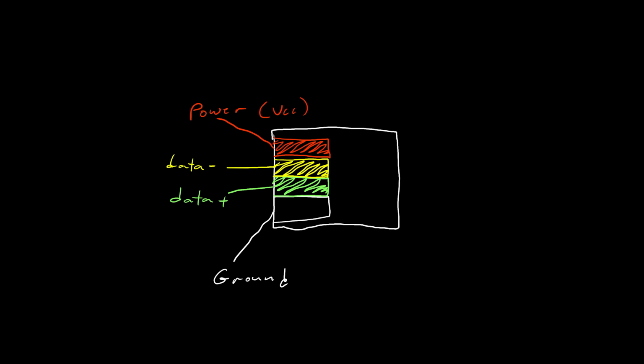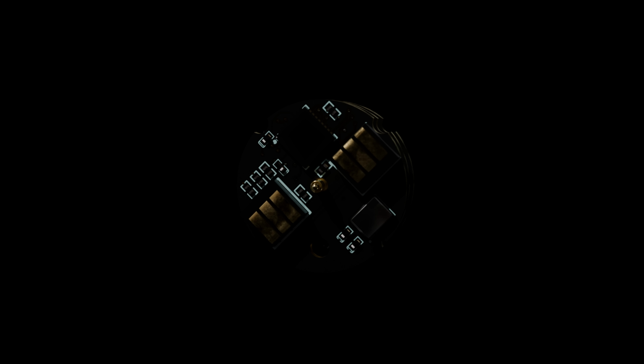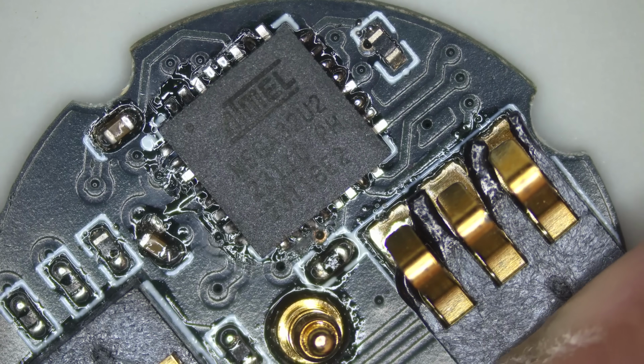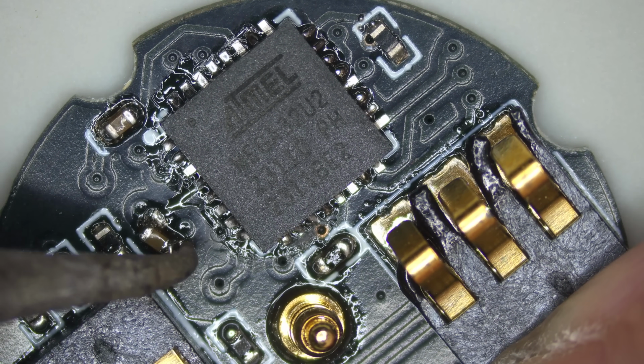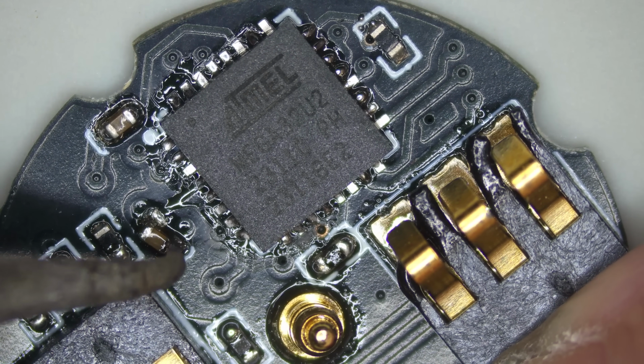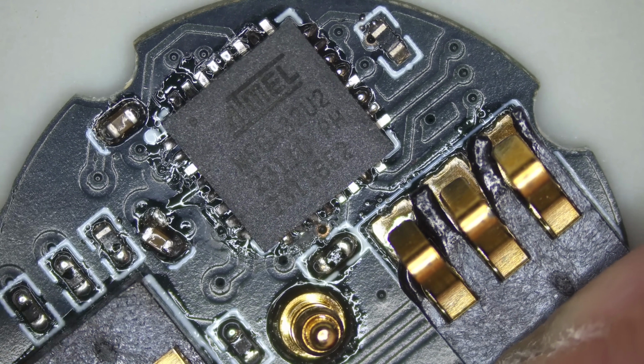Working backwards from the cable, it will connect to the device's PCB stack through a placeholder riser. This is a layer that just increases the height of the stack, so that in the future you can swap in an expansion device. After that, it connects to the main board of the device. The purpose of this board is to handle all inputs, accessories, USB devices, and read the BCI data. I use an Atmega32U2 microcontroller for this purpose because of its built-in USB support, but ideally this role should be delegated to a more powerful processor in the future.